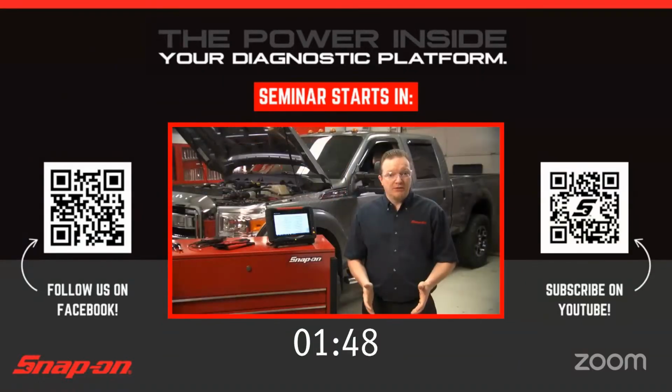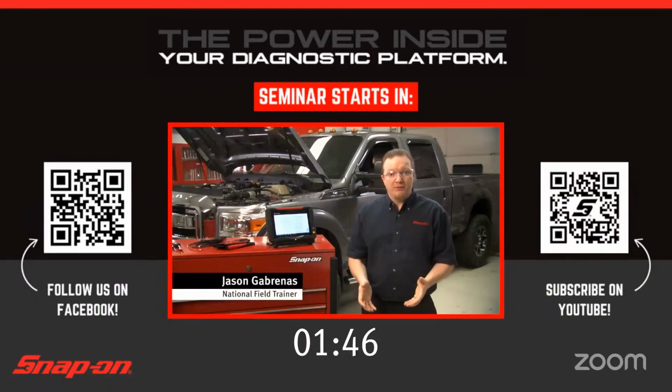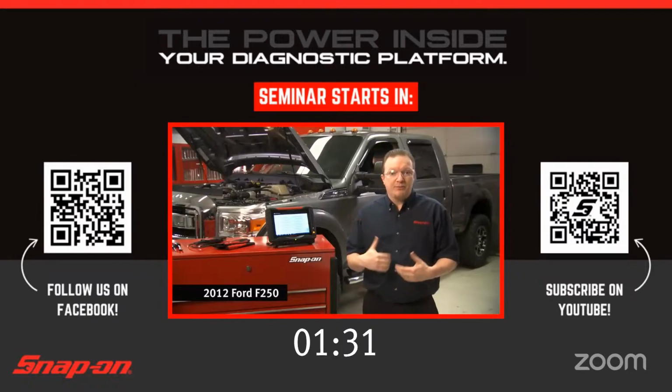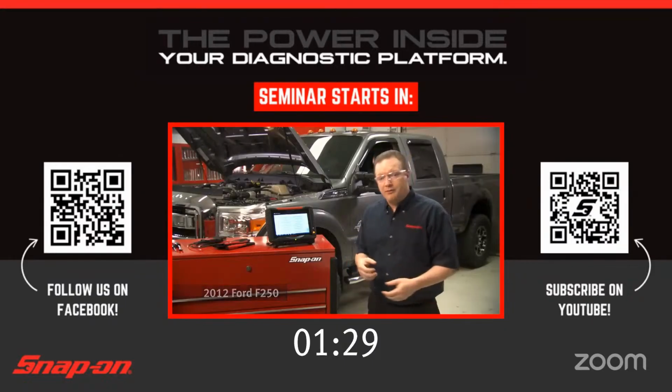So on a lot of vehicles, especially diesel trucks, when you replace a fuel injector, you often have to code that injector into the vehicle's computer. What that coding does is tell the computer how much fuel that injector is going to flow, because every fuel injector is going to flow a different amount of fuel. So on this Ford truck, it's a pretty easy procedure, so let's walk through it.